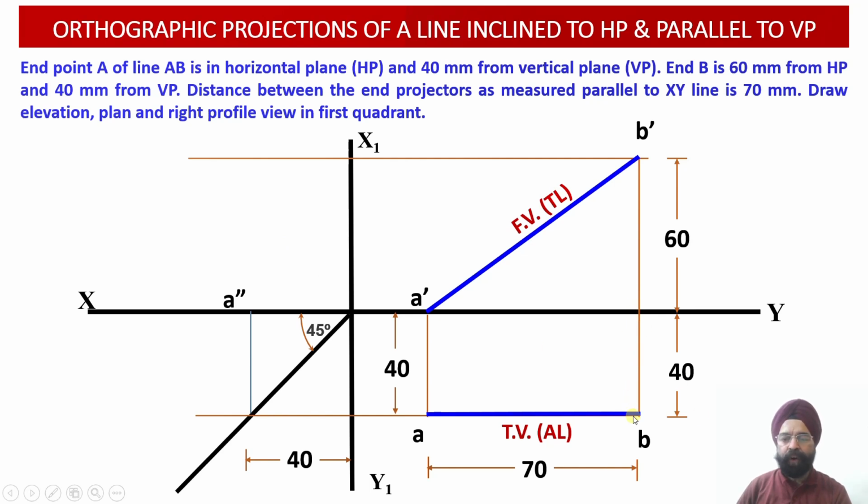So please check, from the point B we are going to draw a horizontal projector line and extend it till it intersects with the transfer line, which is drawn at the angle of 45 degrees. So over here we are going to obtain this particular intersection. That is, this distance is 40 millimeter. That is, this distance of 40 millimeter in front of the vertical plane from the top view has been converted to 40 millimeter in front of the vertical plane in the profile view projection.